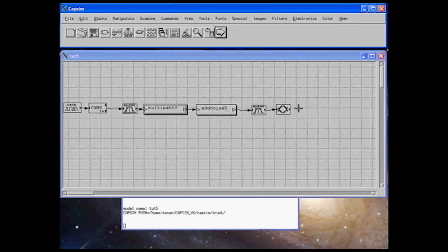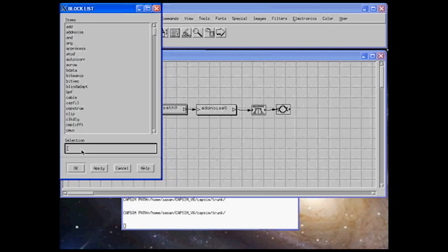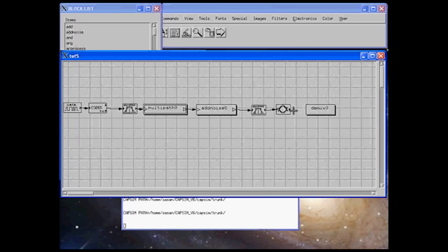So the first thing we're going to do is go ahead and grab this block called Demux. This is a very useful block, very powerful block. The Demux block actually takes, let's go ahead and connect it, the input sample stream and demultiplexes it to the output streams depending on how many are connected to it. So for example, you can take the input stream and split it off into various other streams, and in each case, of course, you might achieve a downsampling.